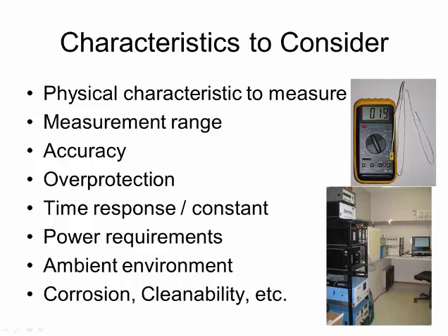For example, if you're looking for a flow meter, you need to know what type of flow you are trying to measure. Some meters measure gas flows, some measure liquid flows, some can handle liquids with solids, and some cannot. Another characteristic to consider is whether the material is corrosive. If you are working with a food ingredient or product, the meter needs to be cleanable and meet food grade standards. Temperature, pressure levels, and flow rates are important factors too. So it is important that you understand the process so that you can list all of the characteristics that need to be considered in quantifiable terms.